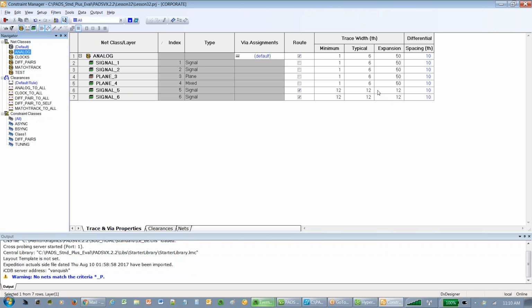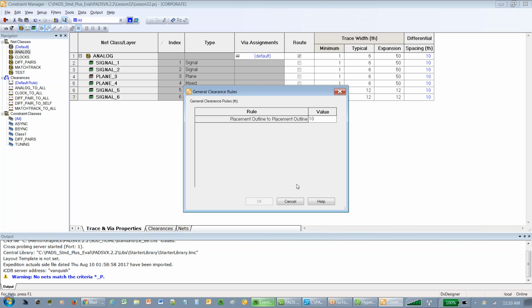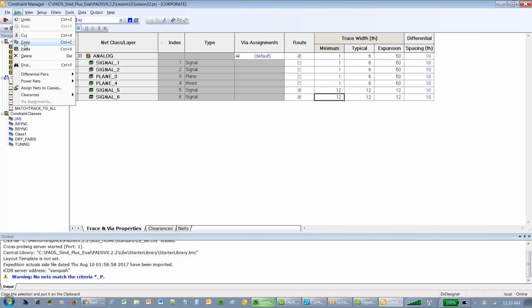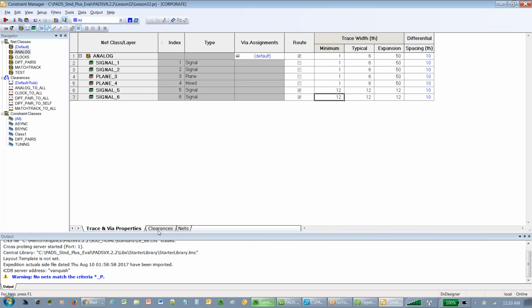Being able to use the constraint management system for doing critical length matching, design reviews, and looking at the design while it's being worked on, all in one central location. So again, the whole process is simplified. Okay, just a couple other additional things in here. You can enter some global design rules for an entire board. We can enter 3D constraints in as well. Let's see, where did that go?